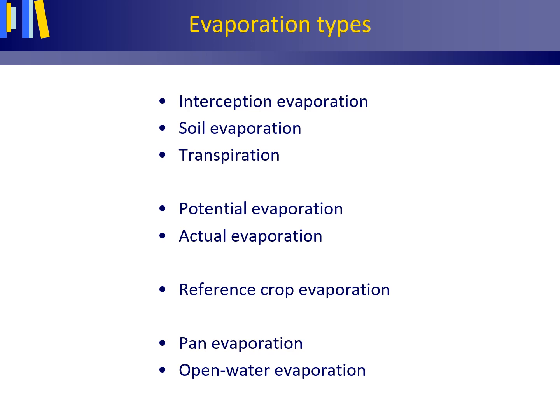This will significantly enlarge the evaporation output from the pan because of the warming up of the water inside the pan by the pan itself. Thus, to obtain open water evaporation rates from pan evaporation data, the pan evaporation values need to be multiplied by a pan coefficient, a fractional value larger than 0 and smaller than 1 that depends on the type of pan used and the time of use, the season.